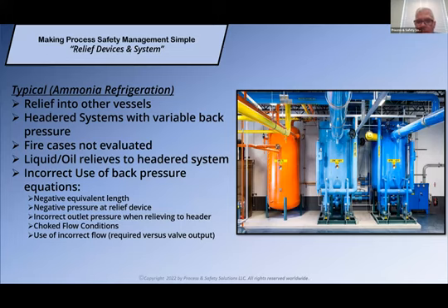For example, if you have oil relieving into your relief header, then since oil is not going to evaporate off, it's just going to sit in there, it's going to affect the performance of any relief valve downstream of that, and eventually you could affect all relief valves if it's going into a headered system. So oil, things like that should not be going into the headered system. They should be going in other places such that you're not affecting the performance of those relief valves that are in there, even if you have drains in there.